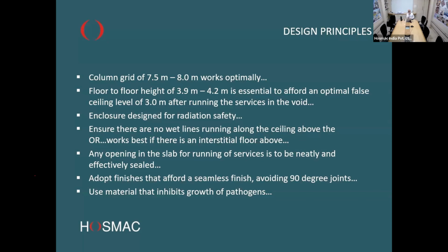The other important element that we need to work towards is that the enclosure should be designed for radiation safety. So maybe Abhishek, if I can draw on you a little bit here, we typically go with a 9-inch brickwork to ensure that the AERB requirements are complied with, so that there is no emission of radiation from equipment like the repeated use of a C-arm or any imaging equipment that we use inside the operating room, especially if we are using it very prolifically.